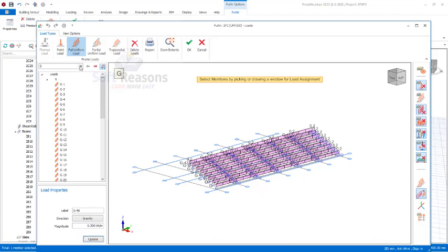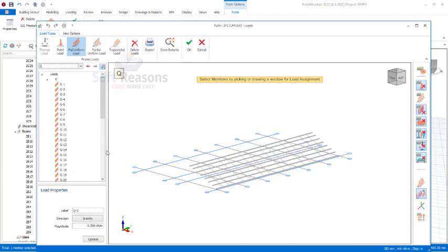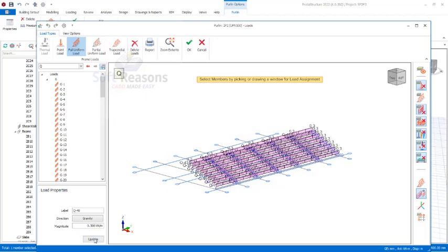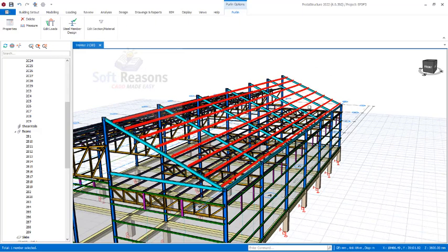We'll come over to the Q load. Select the Q load. You see for the Q load, there's no load right there. So we need to key in the value of the Q load to be 0.3. Then we select all of these members just like this to have the load applied successfully. Click on the update and OK option. So we have applied load on this polyline successfully.